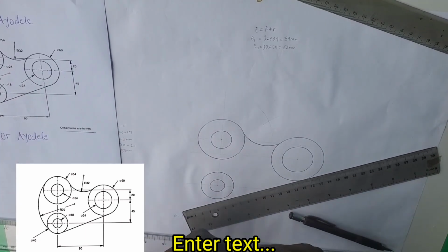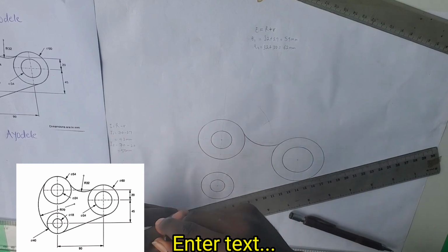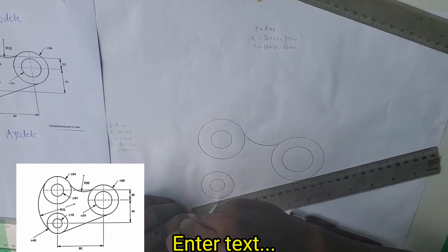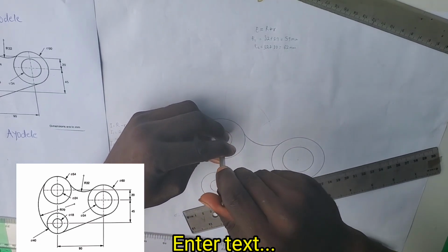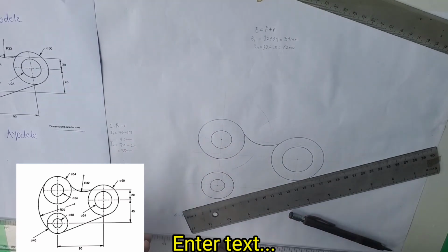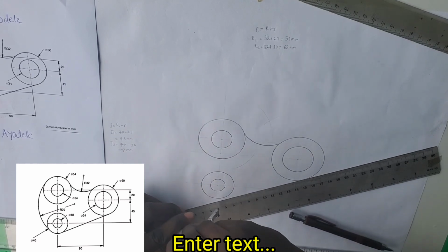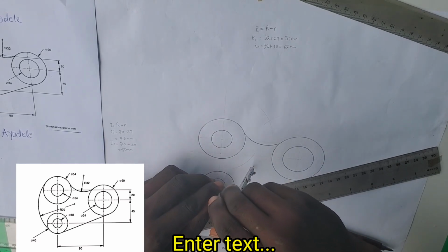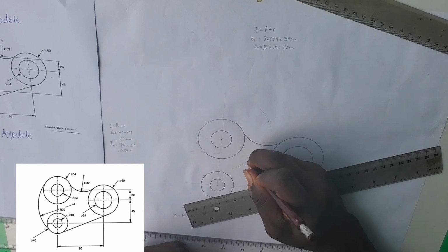Now let's use it and draw 50 millimeters. So let's take 43 millimeters first from here. Strike an arc. Your arc should be faint. Then 50 millimeters from here, which is 5 centimeters. I'm going to keep on saying that. You should be used to it by now. 5 centimeters. Mark the arc. Then this is the point of intersection of the arcs.